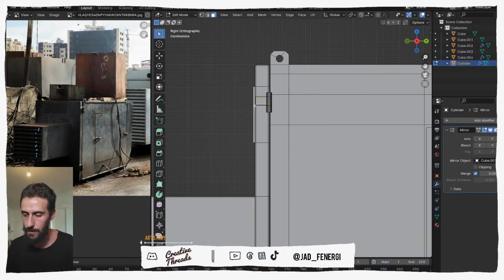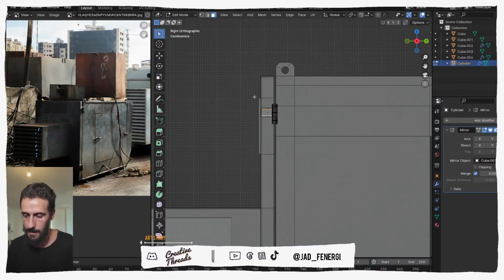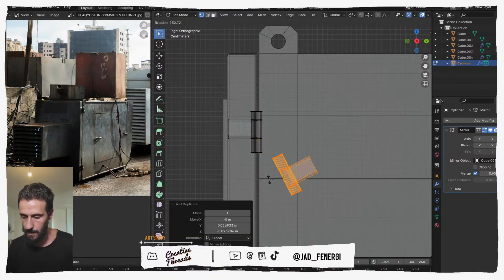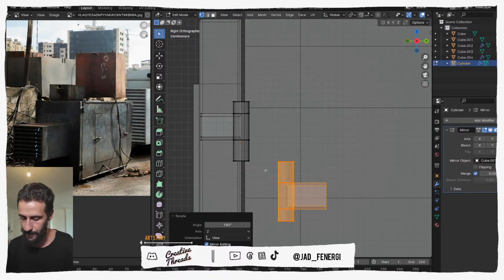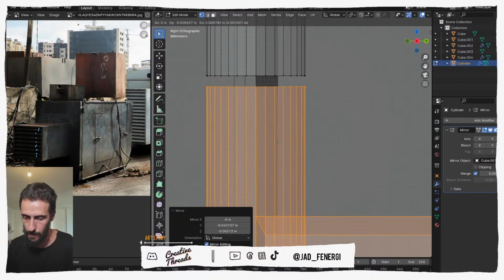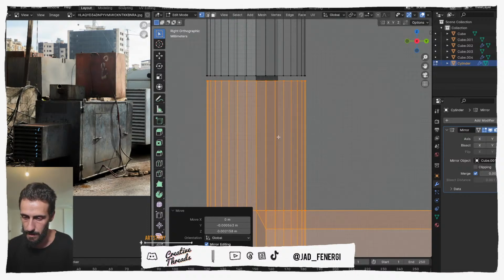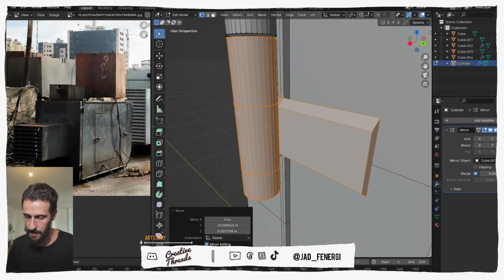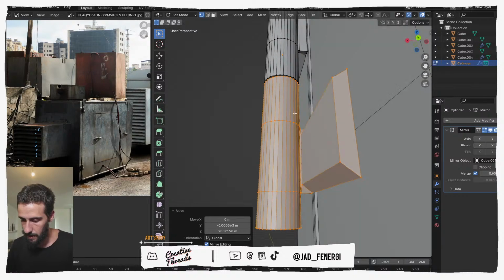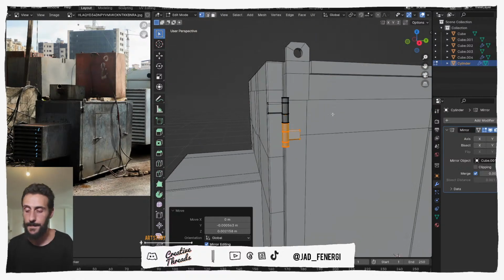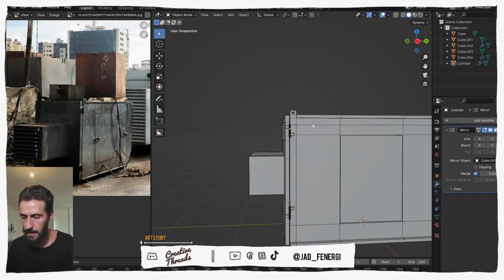So what we can do is we can go to edit mode, Alt Z, grab all of this, Shift D to duplicate, rotate by 180, yep. Then G, just gonna do it visually because I don't want it to be 100% perfect actually. And now, as we press on the period, just want to make sure that, okay, that's fine. Yep.